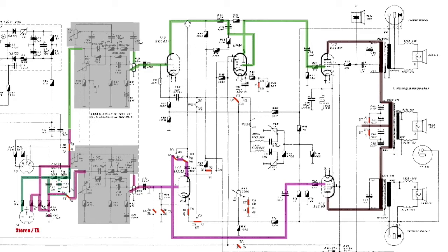That triode then has this signal here, which we looked at before. It went down here and it met two open switches. But if you disconnect stereo, those switches will no longer be open, and you'll end up with a signal going through here and down to drive this pentode. So that is driving that directly, and that is also driving this one, inverting, so you get the same effect on the two output pentodes. One push-pull function and two single-ended functions.